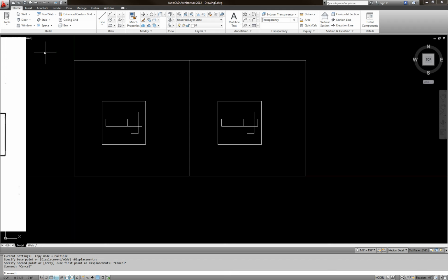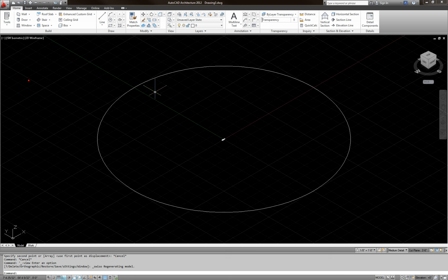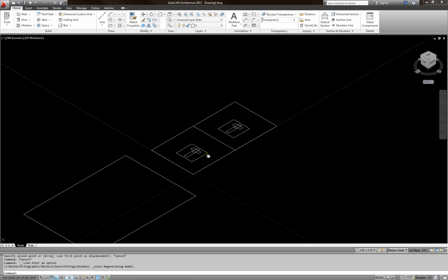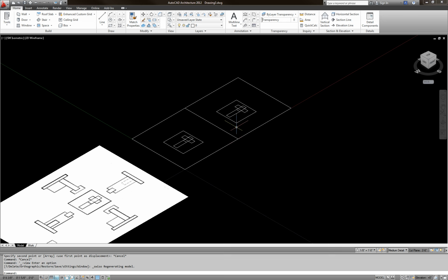So in this case, what I'm going to do, I'll go to this top view, change this to isometric view, guys. Okay. So now I'm going to extrude everything from this ground plane. Okay. So EXT for extrude. See that extrude? Click on it. Give it a few seconds.